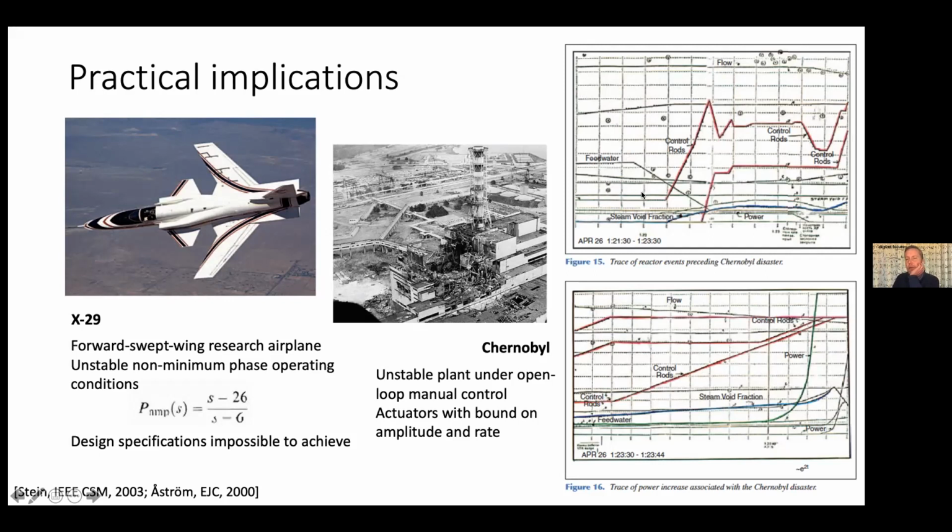But what they did was that during this manual experiment, they inserted the control rods and they lowered the feed water. So they created a situation which was okay, but the problem was that they then removed the control rods. And so they were down with very, very low power production in the system. So the top plot here is over some minutes, and then we continue down. Here you see the power. There was basically no power production, but the control rods were almost out of the plant.